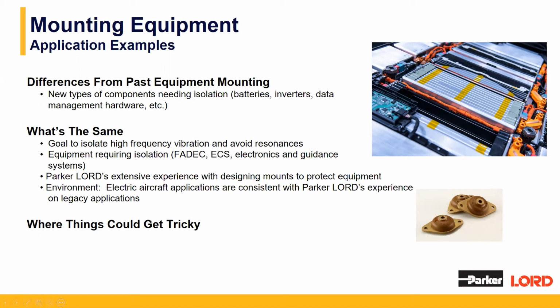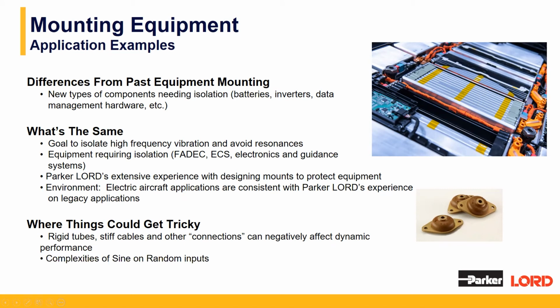Some things to keep in mind here. For our single degree of freedom systems we've been discussing, they're great to understand the concept of vibration isolation. However, considering actual systems, the rigid tubes and stiff cables or other connections can negatively impact dynamic performance, since they will act like stiff springs with a low loss factor. As we see more rotors on aircraft, sine-on-random type input conditions will become more common, and these can be complex to predict. And finally, elastomeric isolators are not good thermal conductors. As we've all been hearing about, thermal management and dissipation are related to the ever-growing need for increased battery and efficiency capability.